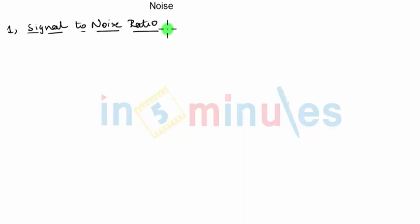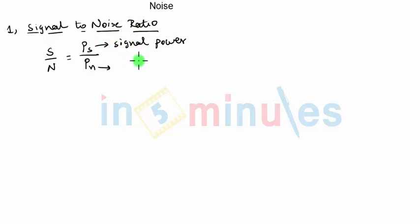And hence we define a ratio of signal power and the noise power, which is given as S upon N. Here S is the signal power, which can also be written as Ps, and N is the noise power, which can be written as Pn. So this is the signal power. When I say signal power, it is the power of the signal which is of interest, which is the information signal; in simple words, the signal which must be present in the communication system at that particular point.